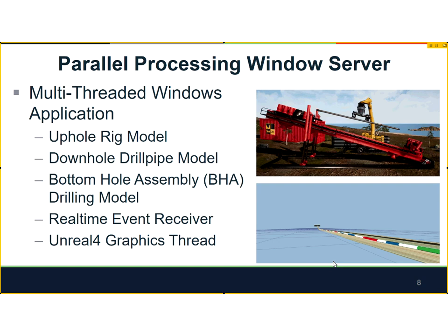It's got two clamps, one that will hold the drill string fixed and another that will twist the free pipe relative to that and force them to make basically a super tight joint, so that when you have a mile of pipe underground and you put a high torque, anti-torque, you won't accidentally have a separation halfway down underground and lose half your drill string.